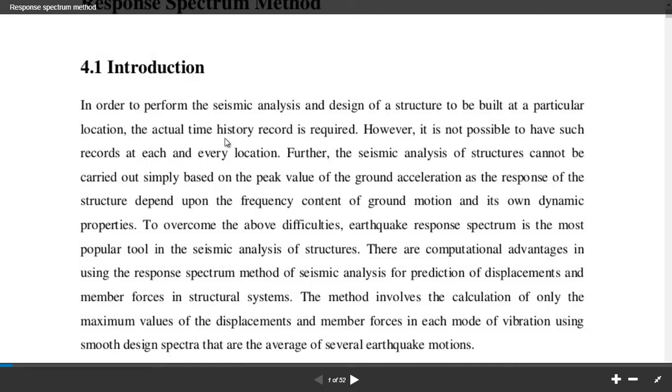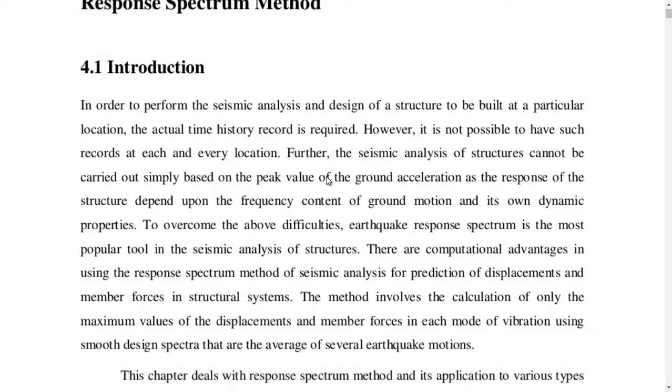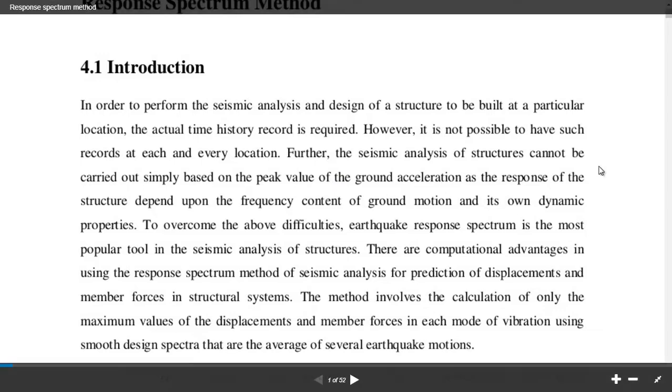We can't have time history records for each location. Further, the seismic analysis of structures cannot be carried out simply based on peak values of the ground acceleration, as the response of the structure depends upon more than the peak values. For example, let's say the peak acceleration is 0.3 or 0.2. The response of the structure depends upon the frequency content of the ground motion and its dynamic properties.